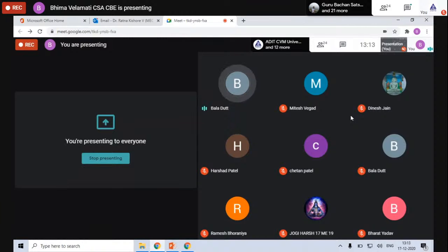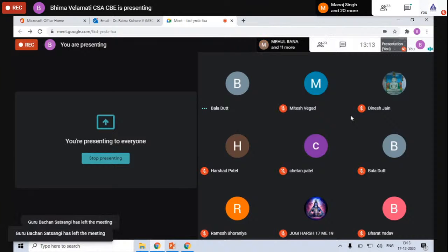So sir, most of these flows, especially when you go for a large flow rate, will be turbulent. So the turbulent flow would affect my solution. Numerically, what we do is solve for different turbulence models. The best turbulence model for URANS that is available is SST k-omega.